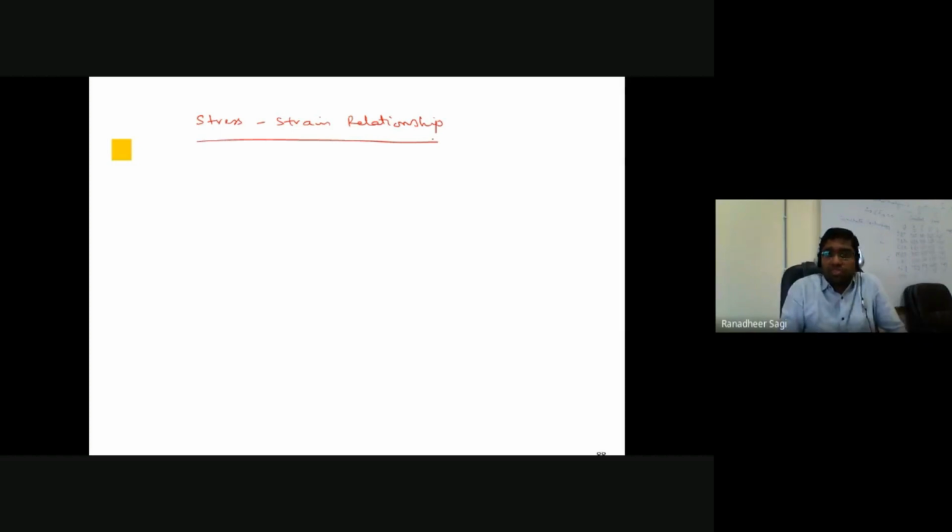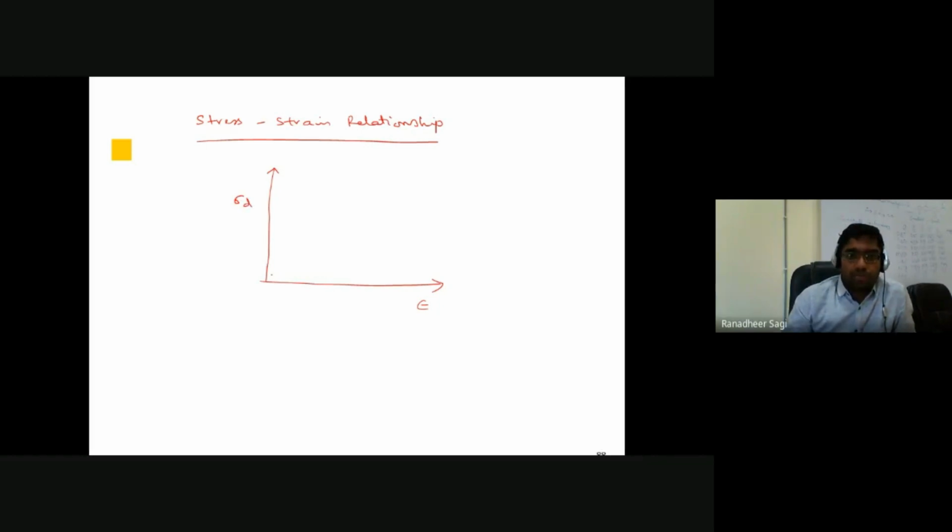of the soil. Okay, so for that, let us look at some stress strain relationships. The corresponding stress which was responsible for causing the shearing in the soil sample is what I am trying to look at. Let's say it's the deviatoric stress which is responsible for causing the shearing in the soil sample. So for that corresponding strain, what was developed in the axial direction, that is in the vertical direction, how your deviatoric stresses getting developed in the soil sample are getting changed. I hope we have already seen this kind of typical curves.